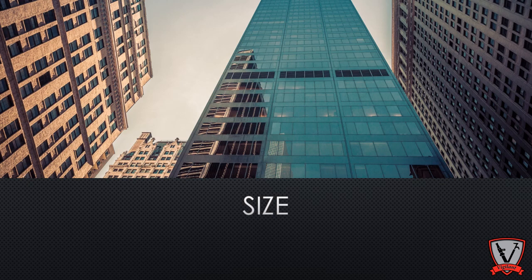Because when we talk about large buildings, we want to define large buildings as a building in which the area exceeds the length of your primary pre-connected lines. So in other words, if I have a 200-foot pre-connected line and my building area is larger than what my 200-foot pre-connected line can reach, then that building is large. That puts the same playing field on every single building that we go to.